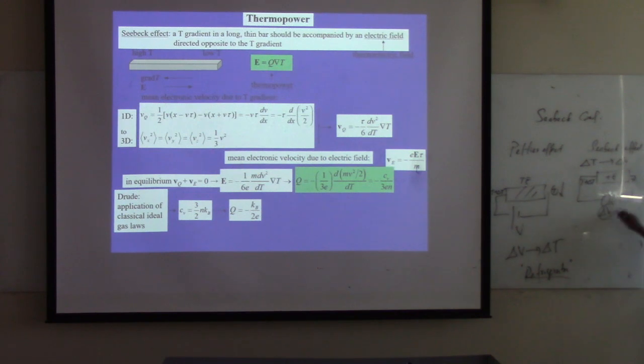Typically these voltages are very small. We are talking about microvolts per Kelvin. But now, because of new materials, we can make this even millivolts. So that means if you put several in tandem, you can make volts. If you can cool both ends, now we can make several volts, even to run a motor.